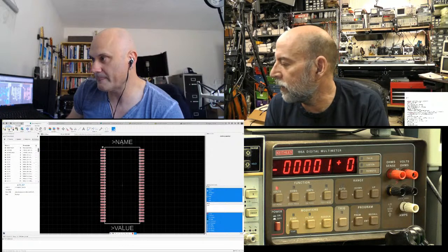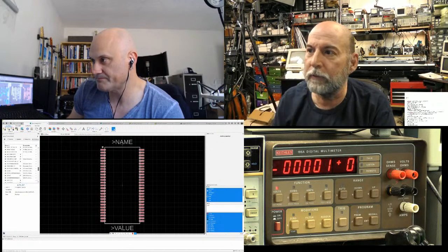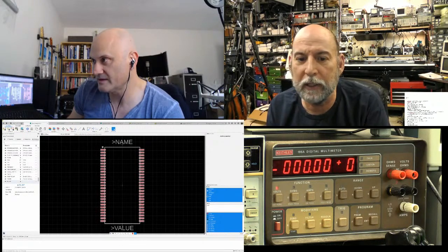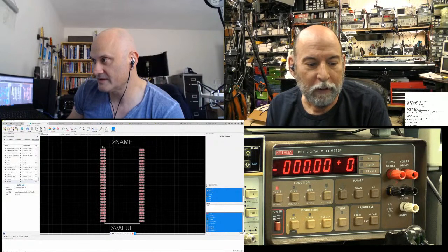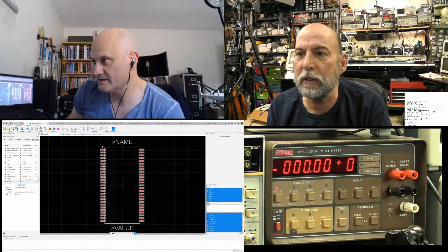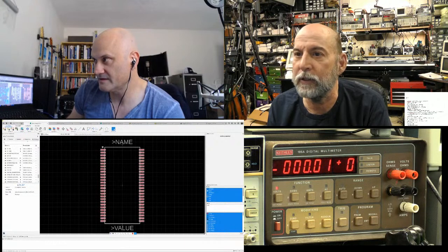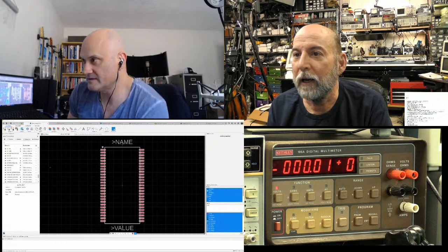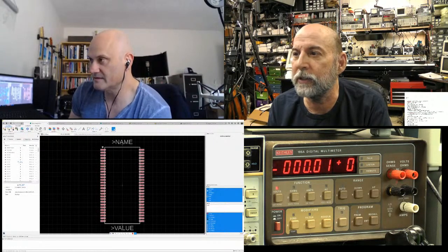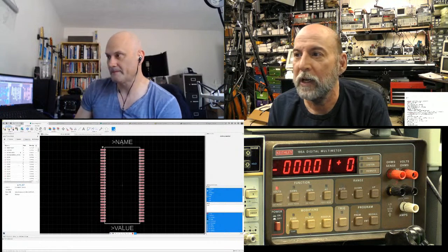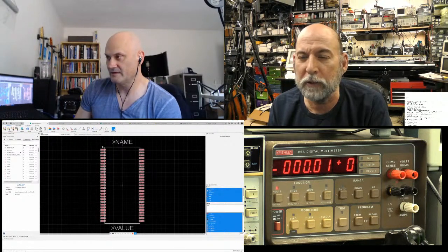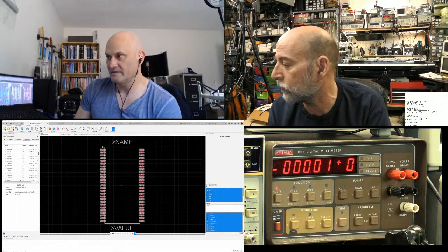So one of the things I was thinking about earlier when we were talking about FPGAs and the Lattice, first off, that with the Lattice, you can still get 5-volt tolerant parts, or at least you could. Whereas if you use the modern Alteras and Xilinxes, you inevitably need some kind of level conversion if you're trying to get to 5 volts.